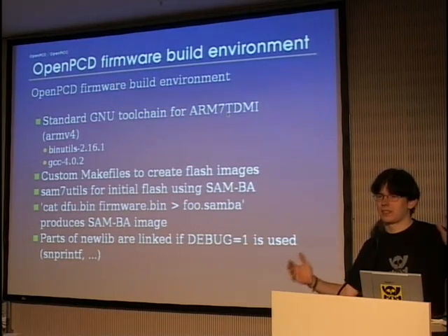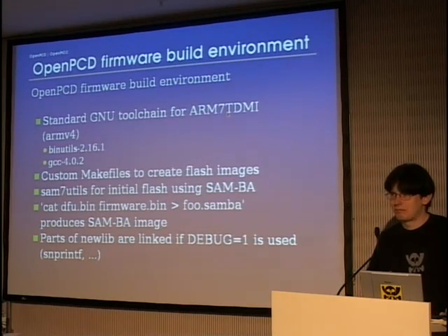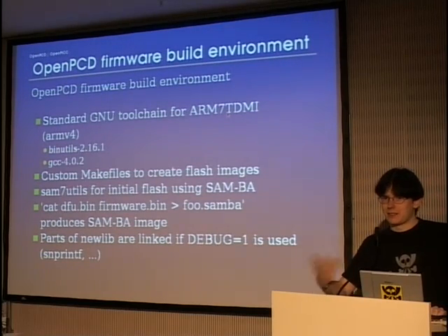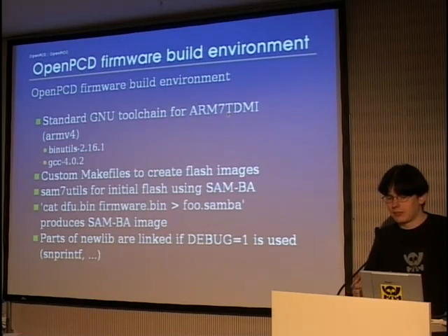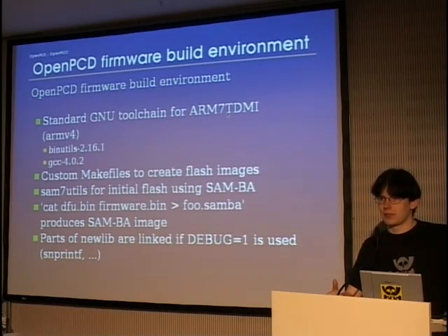That whole process, even though it still contains lots of debugging code, only takes about 5 seconds. So you can actually dynamically reprogram the hardware even from your application if you want to do that. I haven't done that yet, but it's possible. The makefile can create a dfu.bin file, which is the device firmware upgrade.